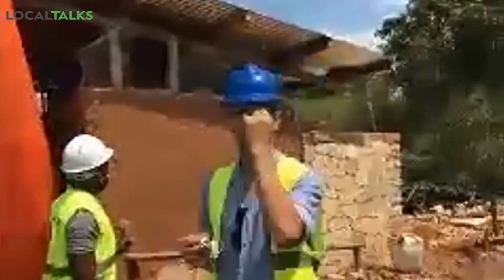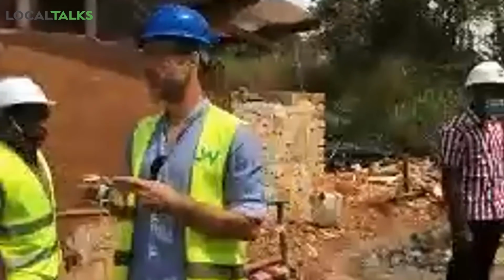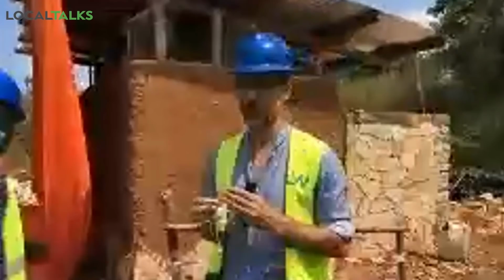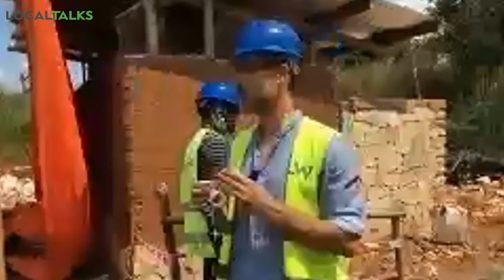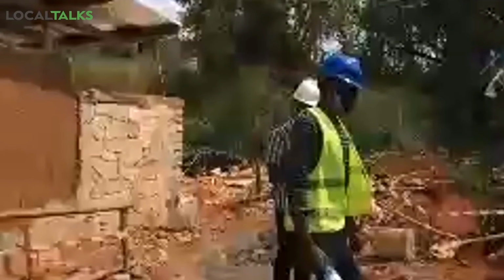So these tiny little buildings have earthbag walls, they have stone walls, and they have wattle and daub walls, which is a technology that we want to use in some of the partition walls in the admin section. So we basically chose to squeeze that all into one little building. Obviously the major rectangle that you see there, which has now started to be plastered, is an earthbag wall.